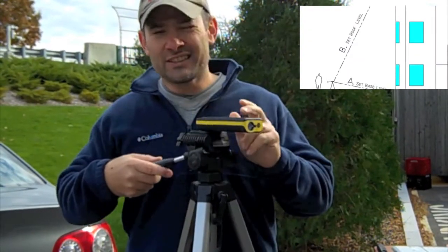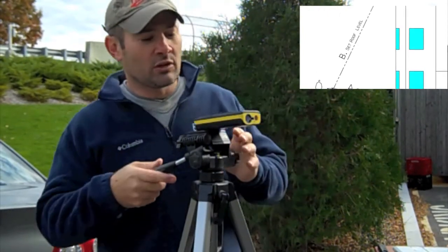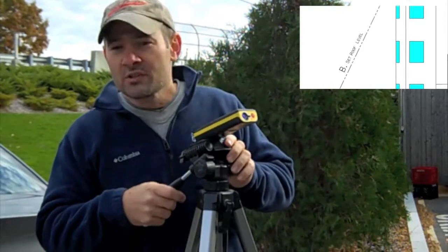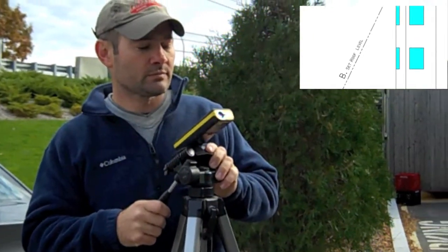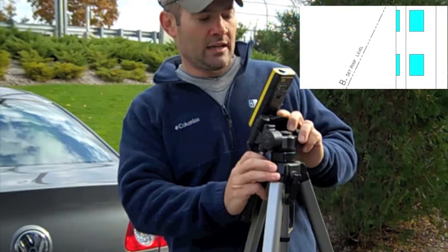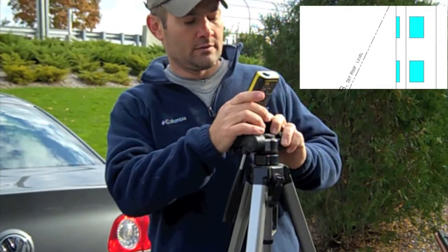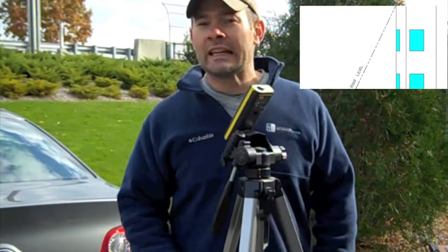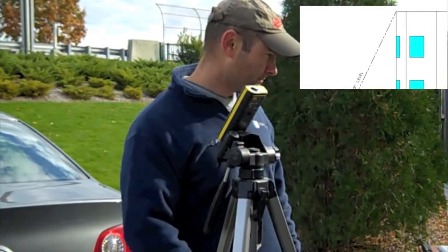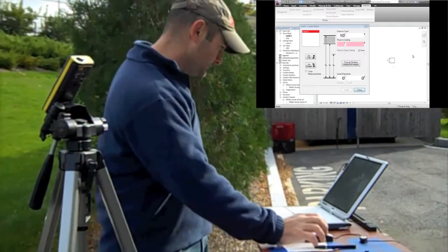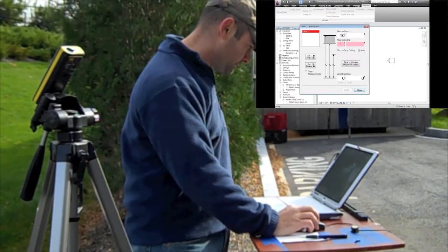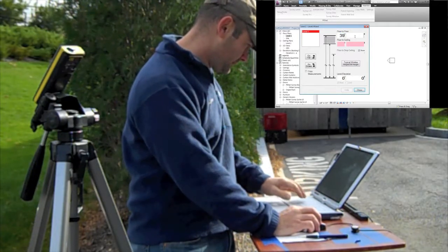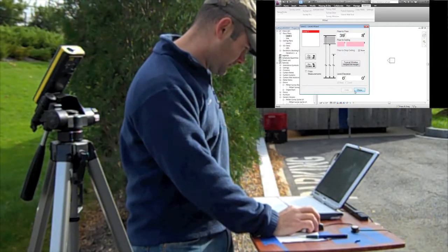So I got that, and there's a tiltometer in the Disto, and as I scroll up the building I can see different level information, but right now I want to just peg it to the top of the roof. And it's at, got it, 39 feet and 8 inches. Here we're using the levels wizard that lets you insert levels as you encounter them on the building, either manually or through Bluetooth transfer of the rangefinder. Use whichever works best for you.